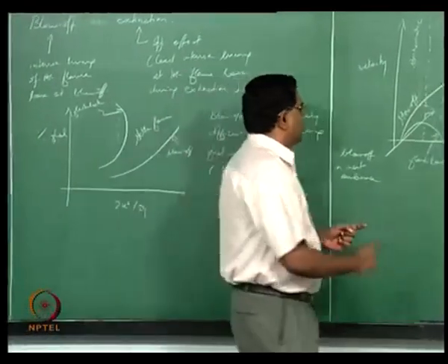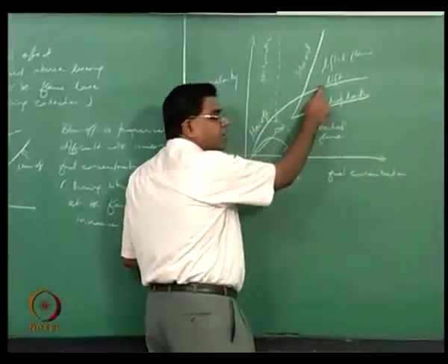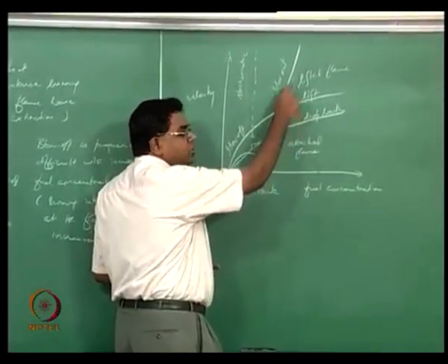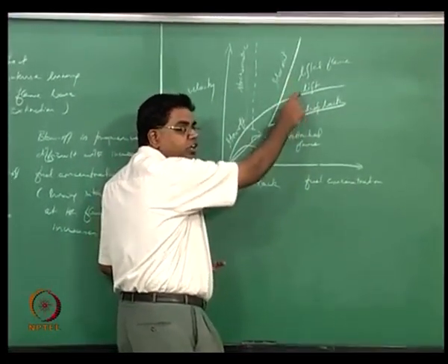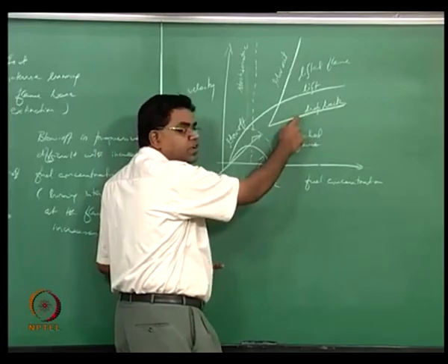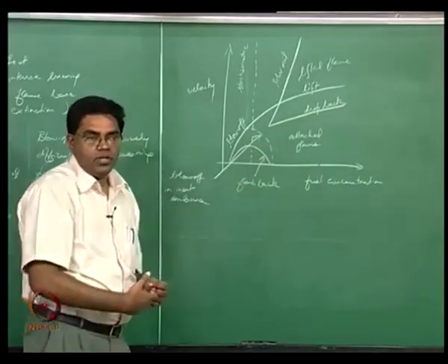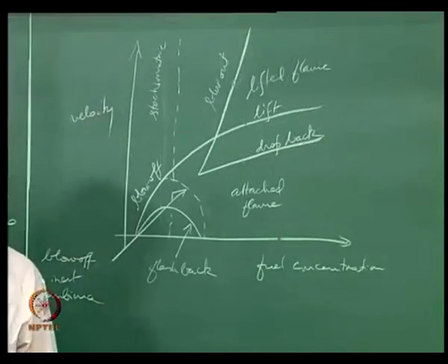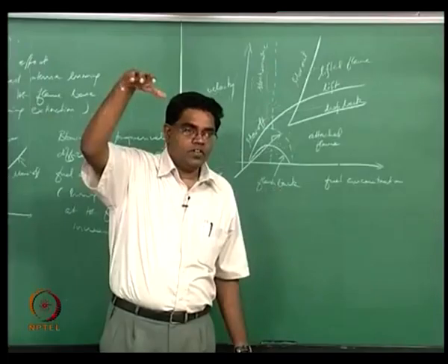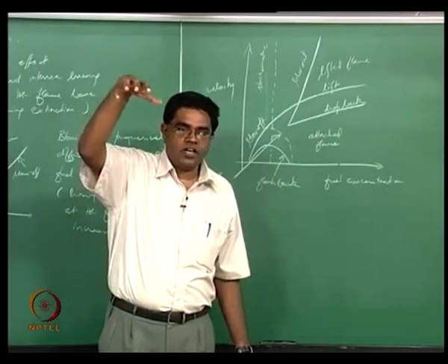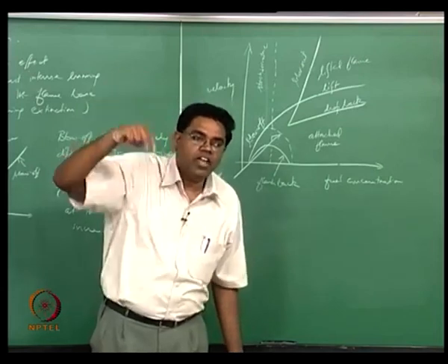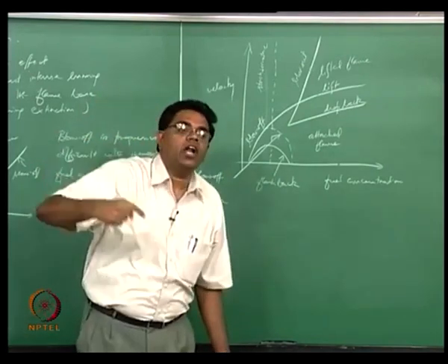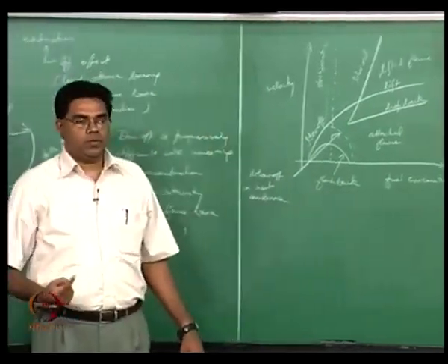So what's going to happen now at that velocity is not going to actually cause a drop back right there. You need to come down to a much lower velocity for the drop back to happen, because now the flame has found a new home where it has got stabilized and it's beginning to get comfortable there. It's going to stay there even if the velocity were lower and would allow an attached flame to happen.